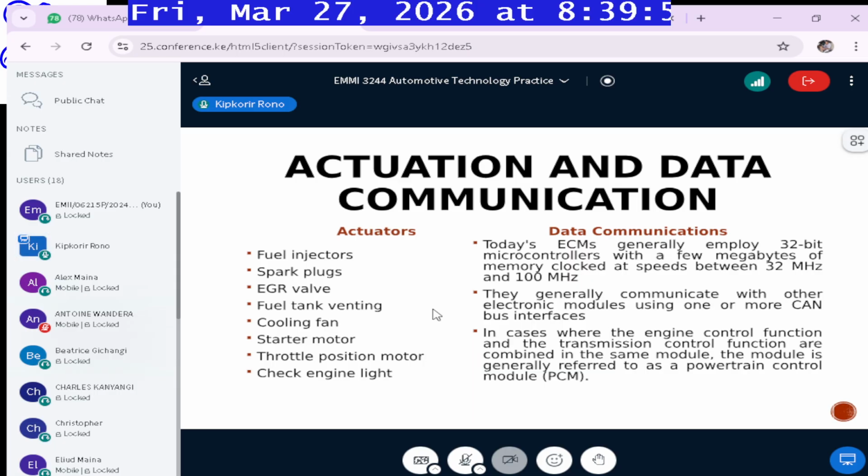So when there is usually the oxygen sensor, it takes the readings before and after the catalytic converter, and then it will send information to the EGR valve, say for example, to open. Okay, so the EGR valve simply carries out instructions. Also, the EGR valve usually does not come into play, especially when the vehicle is moving at, say, usually below 50 kilometers per hour. So it's only once you are cruising that the vehicle may simply instruct.